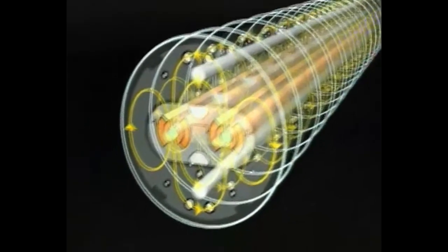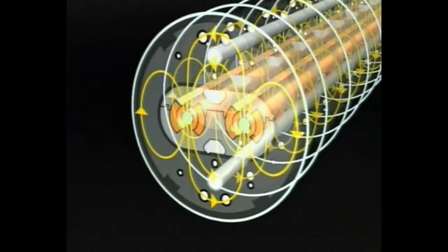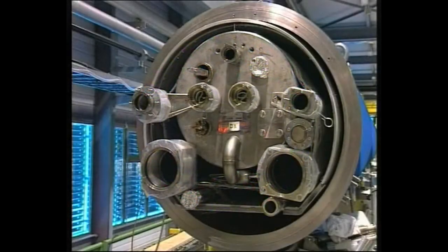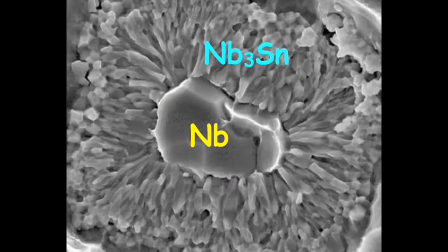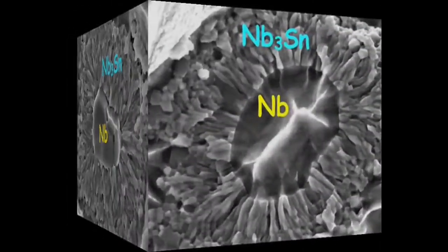But of course we immediately were aware that we encountered new problems, completely related to the fact that niobium tin is a brittle material. You have to heat treat the coils that are wound. So after you have made the coils, you have to heat treat them at 700 degrees, so that's very difficult from an engineering point of view.